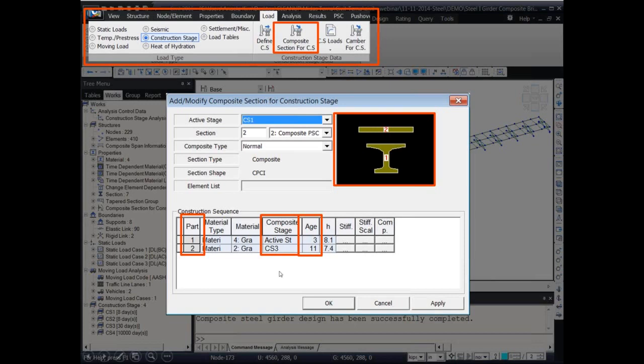So over here, age is to reflect the compressive strength of the material that you selected. So basically, for part 1, I have an age of 3, meaning the girder as the structural element is activated in the program with the stiffness value that the girder gains after 3 days of the pouring. And 11 means the stiffness at 11 days. That's how this material property is activated.